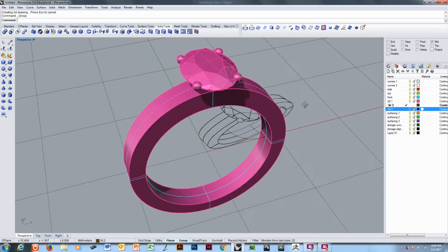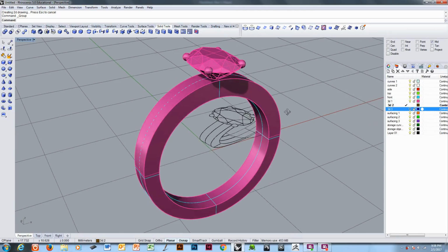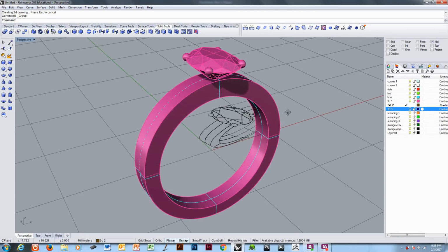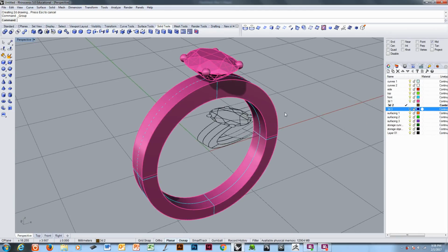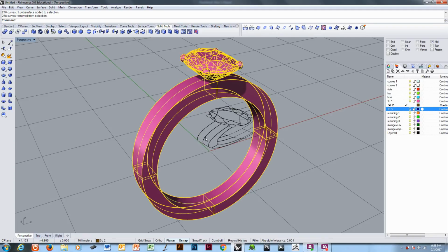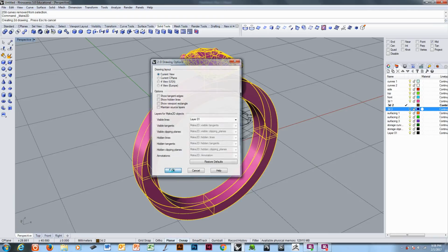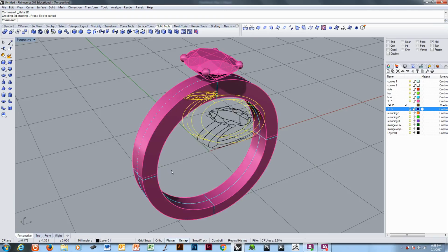those drawings. Now, I'd also like to do a couple where I'm looking primarily at the front of the ring, something like this. So once again, I'll Control A. I'll hold down the Control button and do a crossing selection to deselect the drawings. Make 2D drawing. OK. Group.